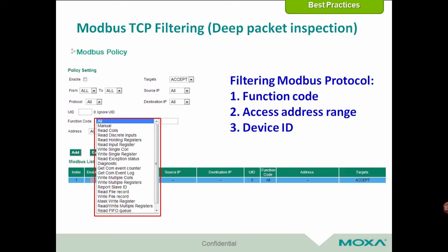Finally, a firewall is only effective if it can filter out the harmful traffic. In industrial control systems, firewalls must be able to look deeper into the application layer data within the packets in order to effectively protect your systems. This deep packet inspection allows you to set up firewall rules at the application level to ensure that you're catching all of the potentially harmful traffic.